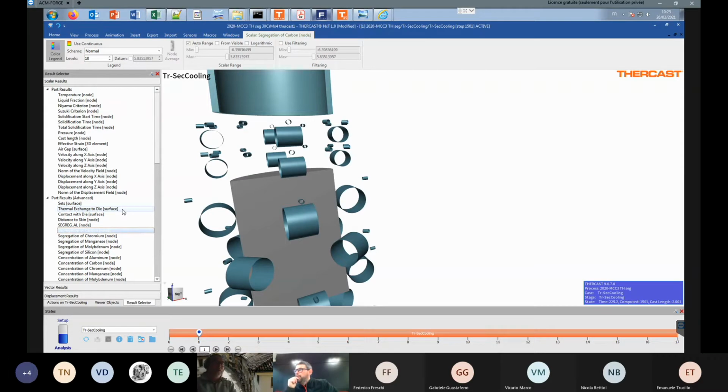To model the macro segregation, we first have to be quite accurate in terms of micro segregation at very low scales, and then we also have to model the flow accurately. So Darcy law and the material parameters linked to, for example, Darcy law in the mushy zone.